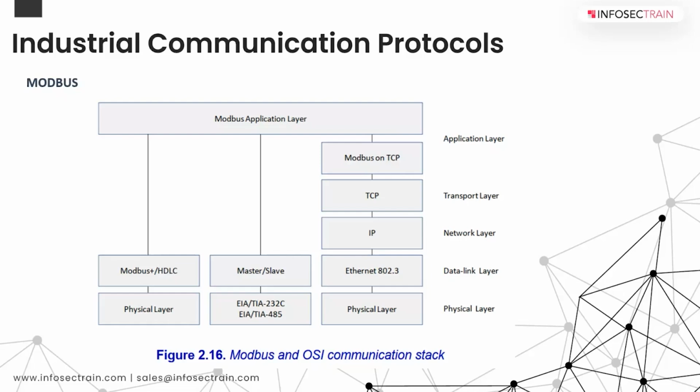to connect PLCs to IEDs, or intelligent electronic devices, especially in the electrical or power industry. And even those are slowly moving; the trend is towards a generalization of TCP/IP even at the lowest levels. Like I was saying, level 0 to level 1 also TCP/IP is being used. So this Modbus protocol is so common in the majority of implementations. It's a master slave protocol.